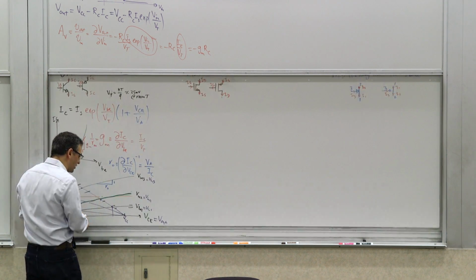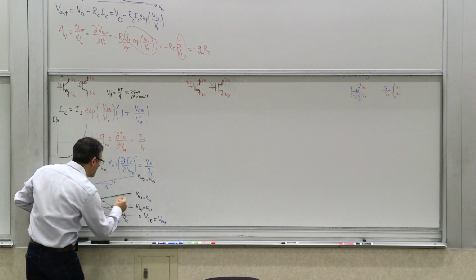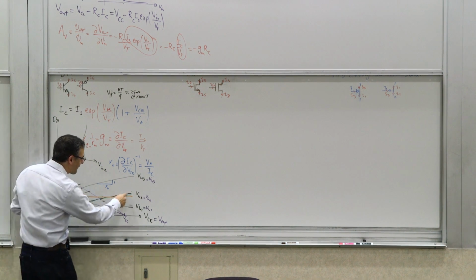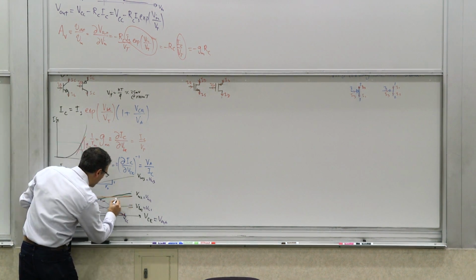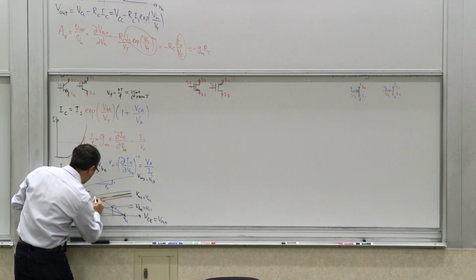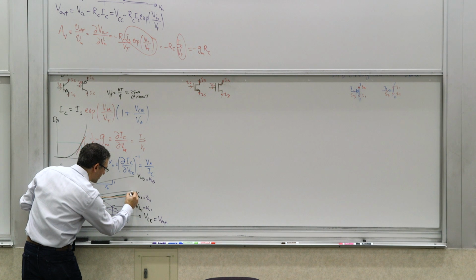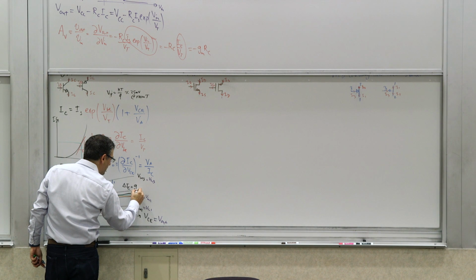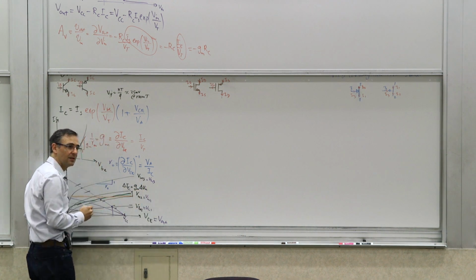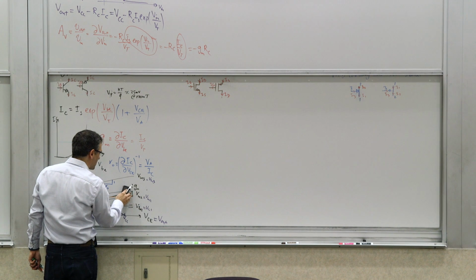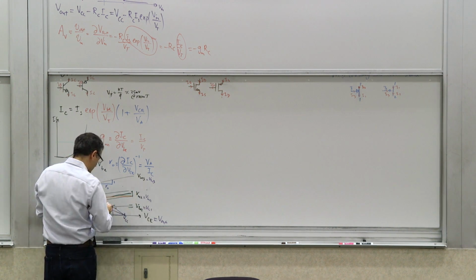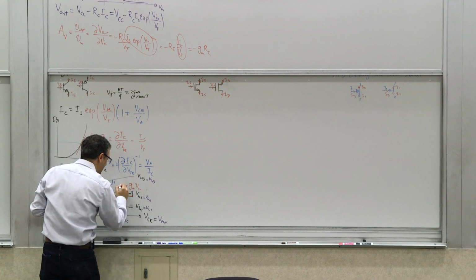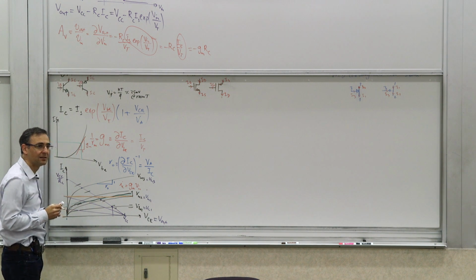Now in this picture, can we also see that? Let's say we use that orange line, that flat line. You can see that the change from one black curve to another black curve, this delta IC, is simply GM delta vn. In our notation, GM lowercase vn is the fluctuation in IC.